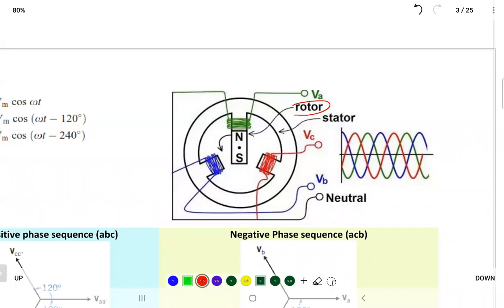You know how voltage is produced, or what we call EMF, electromotive force. When a magnetic field is changing and cuts a conductor, it produces voltage. So when it's rotating, it produces voltage, but because of the shift in time, distributed 120 degrees apart between the green, the red, and the blue, the voltage produced in each coil is separated by 120 degrees. That's how we produce three-phase.